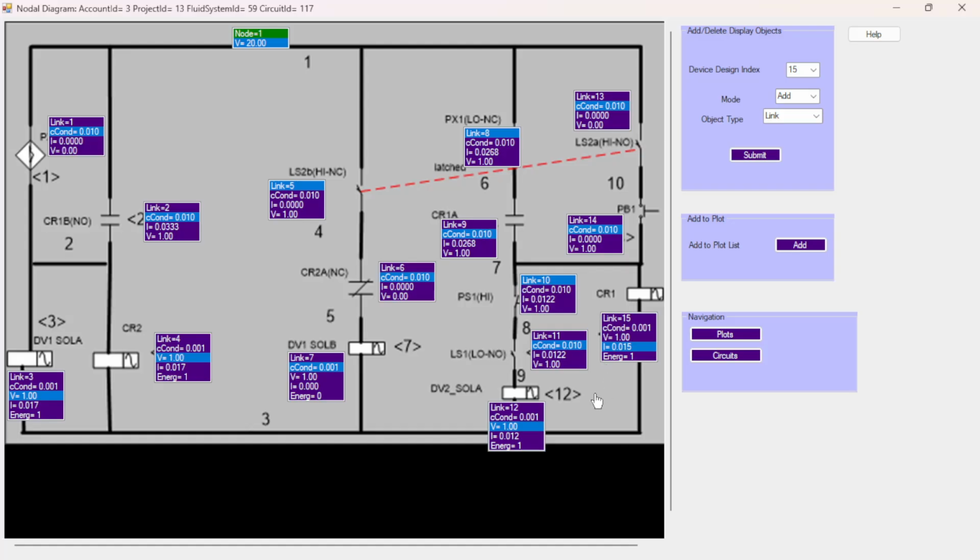You wouldn't look at everything in the same way as I'm doing in this example, but it really shows you the dynamics of the system. And so in this particular case, what we have is a switch. If I change the state of the switch, and you can do that by selecting V, which is the switch, and since this is a manual switch, I can change the state. Then this path is down, but because this switch is closed and this switch is closed, we have current that runs through to energize this relay. But as this relay opens up, then we lose power to this relay.